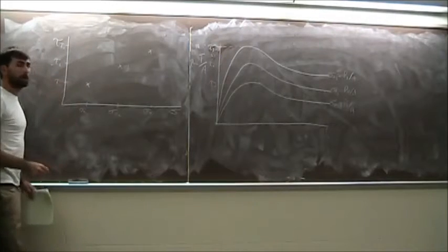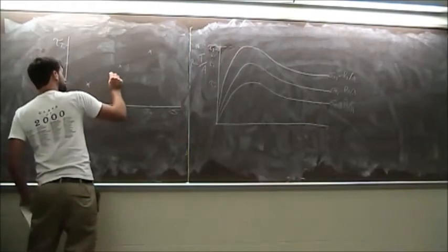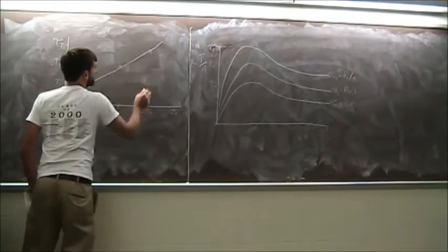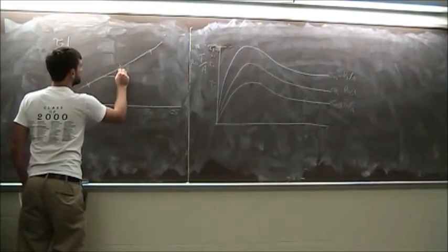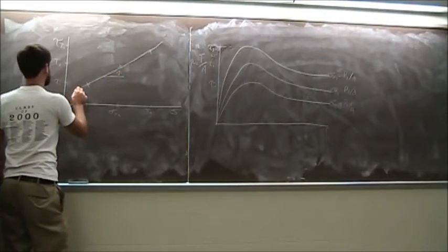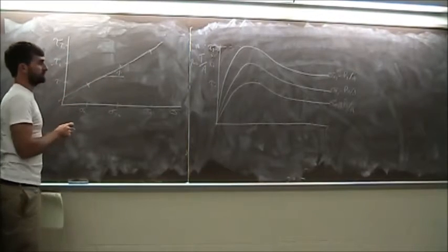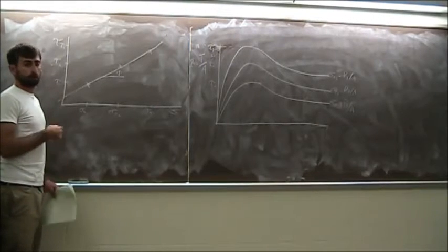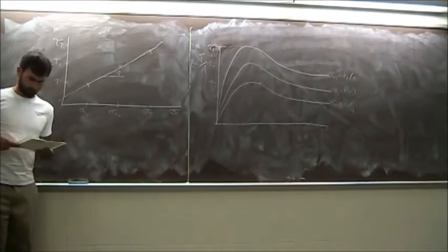So after we plot this up, what we do with the points is connect them with a line. That's your Mohr-Coulomb envelope, and the angle we have here is your friction angle. And if you have any intercept here, that would be your cohesion. But a lot of times these are run on granular soils, and there's not a lot of cohesion intercept for this type of test. Let's see, getting ahead of myself.